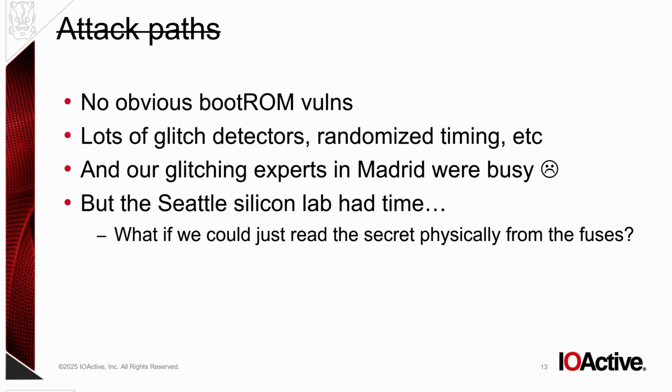Then we go onto the Synopsys website and find out what could be the specific technology being used in this chip. And again, it mentions OTP. It's non-volatile memory, OTP, and it's a 40 nanometer technology fabbed by TSMC, Taiwan Semiconductor Manufacturing Company. We know that our chip is 40 nanometer as well, so it's highly likely it's going to be this or very, very close to this specific technology.